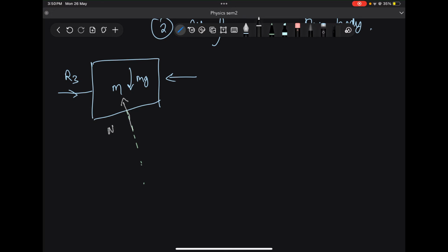And by using my concept of friction that I just talked about, and since I know that the system is at rest, what I can say is that the actual reaction force applied by the wedge will be along this direction, R2, at an angle phi, which is the angle of friction. So I want you to go through this concept once again, because it is very crucial in understanding how friction works and making sums way easier than they actually look to be, right?